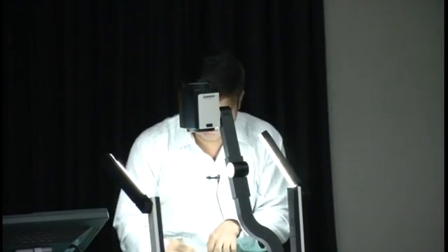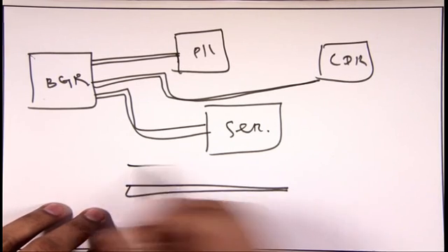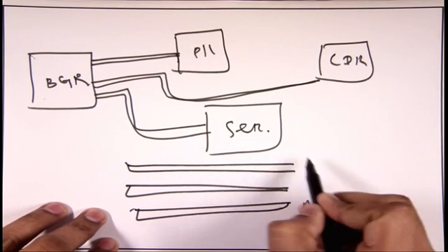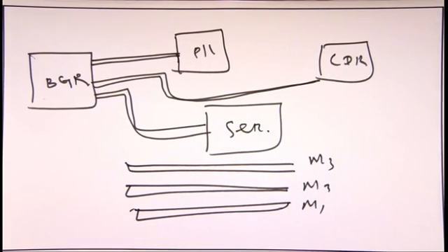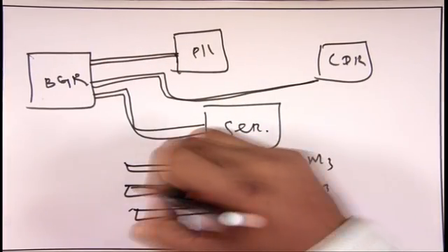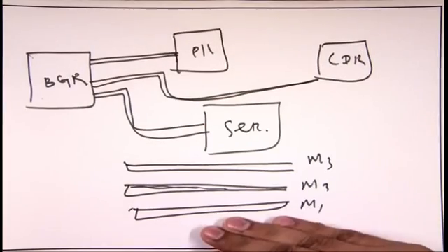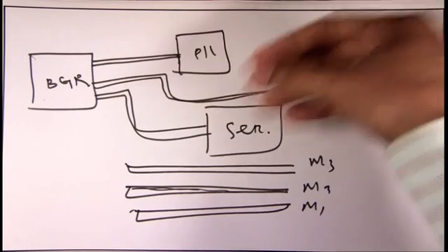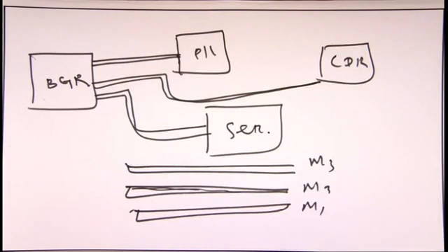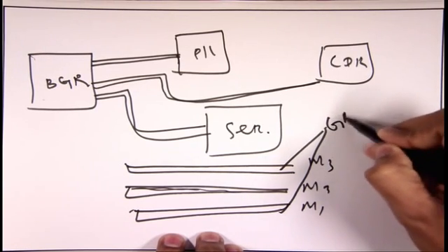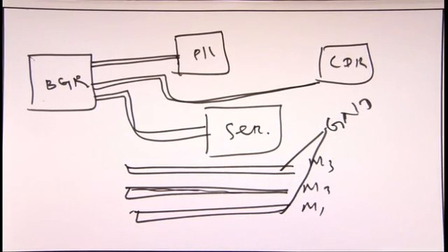This is metal 2 and here metal 3, this is metal 1. The metal 2 is actually connected through the BGR. So power will go through this metal 2. So from the upper side or lower side, the substrate effect and from upper blocks, upper metal, no noise will come. And these two, metal 1 and metal 3, will be ground. Clear? Very simple. So you have the power line and you are shielding it in a 3D way.